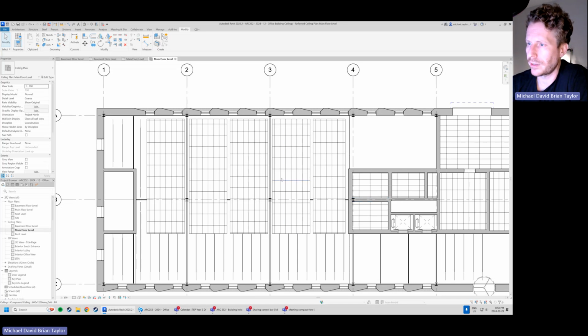So one thing you'll notice is that now, for whatever reason, our panel pattern has actually been adjusted for some reason. I can't say exactly why. Revit's done something funky when we did that mirror. And one thing that you will find yourself doing in the office, this is something that I have done on projects, is we want to use the align tool. The align tool will let us align the patterns between these kinds of elements. Rather than starting over, we can just line up the patterns.